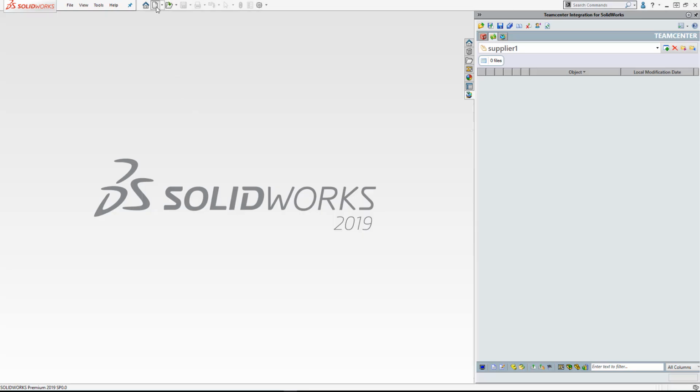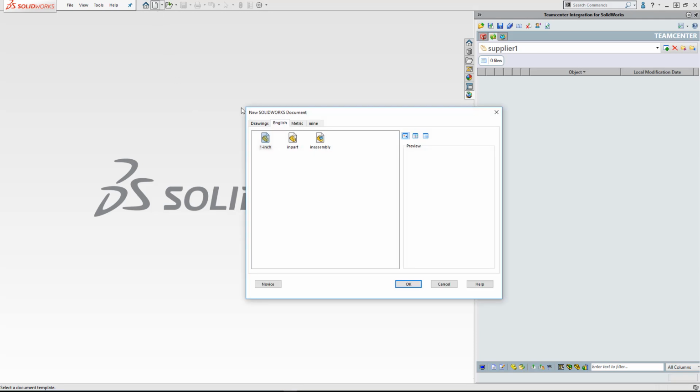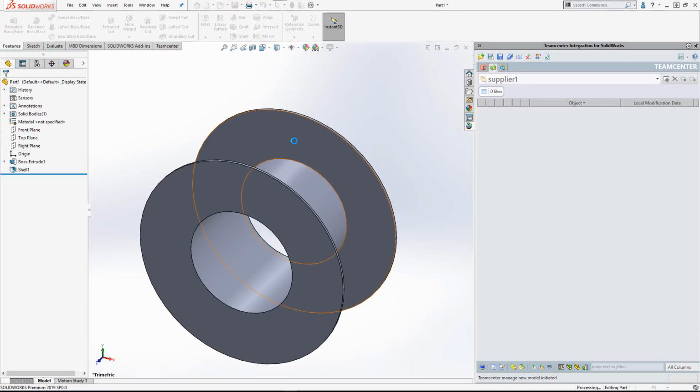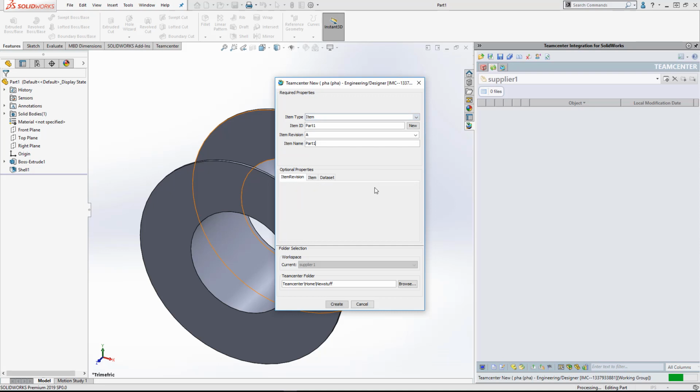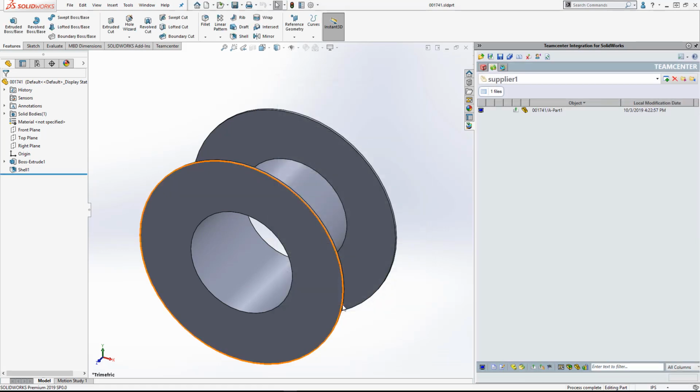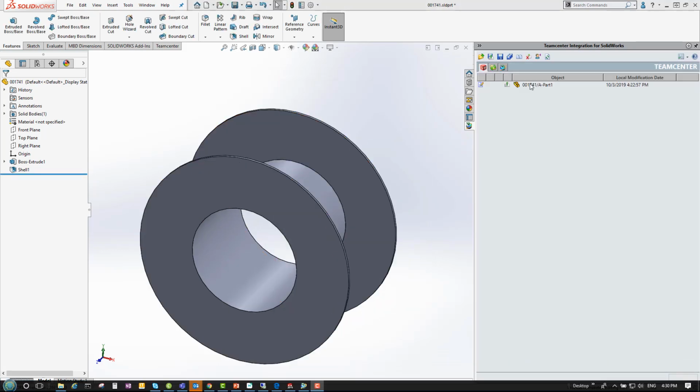Once design templates are imported to Teamcenter, they are downloaded to each user's cache upon initial login. The related SolidWorks preference is updated to point to the cached location, so that users are always working with the latest managed templates. Any folder structure defined in Teamcenter is replicated, at a single level only, in each client's cache, causing the standalone SolidWorks file new dialog to reflect the Teamcenter folder structure.